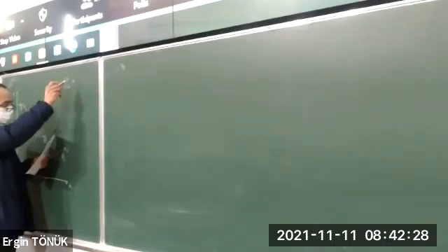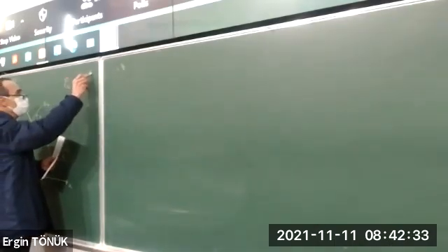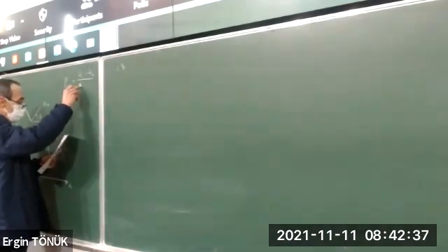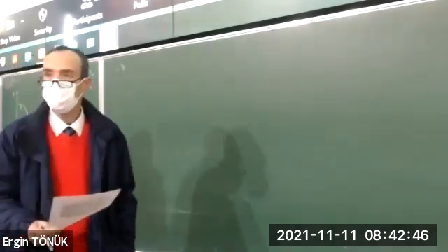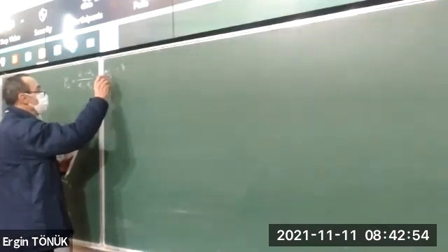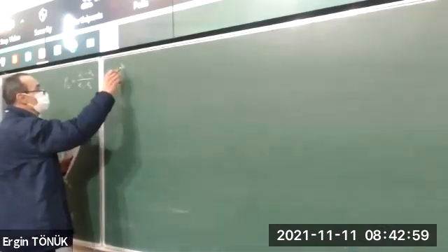So we have determined the location of the pole in the moving coordinate system. The lowercase letters refer to moving coordinates. It was (a1 minus a2) over (e1 minus e2), where e1 and e2 were two shorthands for e to the i phi1 and e to the i phi2. So it's a shorthand. This gives us the coordinates of the pole in this moving coordinate system. And since it's an infinite rigid plane moving from here to there, it has the same coordinates for positions number 1 and 2. No surprise.